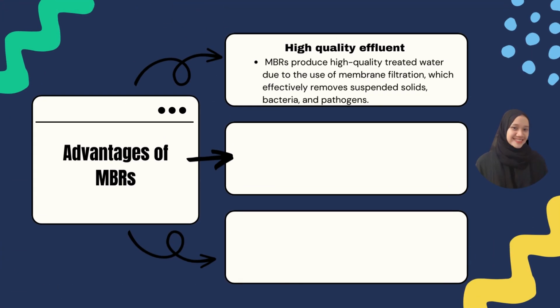Next, we move to the advantages. First, high quality effluent. MBRs produce high quality treated water due to the use of membrane filtration, which effectively removes suspended solids, bacteria, and pathogens. This makes the effluent suitable for reuse in various applications or for discharge into sensitive environments.